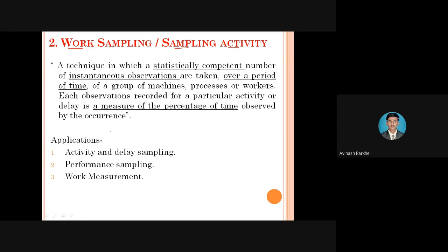You know about sampling operations. A lot of products are available, and from those products we choose some and go for measurement. Sampling is one of the activities performed in the industry. For example, 100 products are available, and from those you take 5 products and measure the dimensions. If all the dimensions are as per the requirement, then the total 100 products are selected for further process.